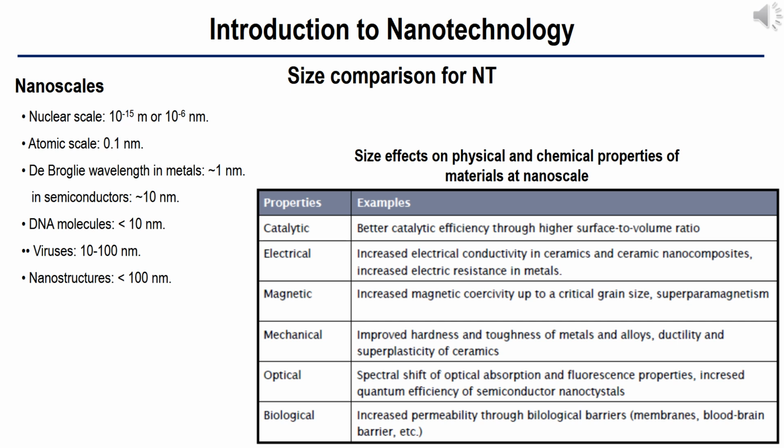For nanoscale materials, electric conductivity can be greatly enhanced due to geometric confinement-guided deformation of electronic structures of the materials. In addition, optical or photonic properties can be dramatically varied. For example, in quantum dots with size smaller than 5 nanometers, the electronic bandgap of the semiconductor varies as a function of the radius of the quantum dots.